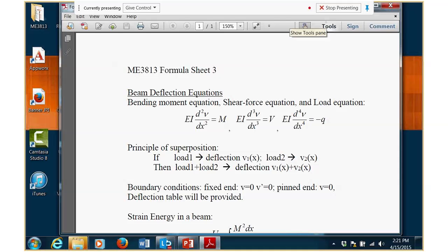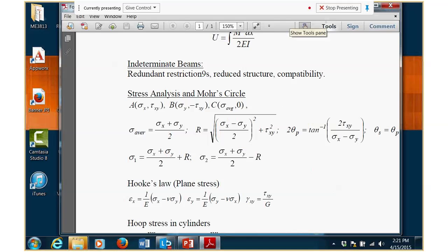And then you can solve that problem as a determinate problem, because that's what we call the reduced structure. And you need to know what a reduced structure is. For an indeterminate structure, you select the redundant load, change it to a force, then this structure becomes determinate. Okay. So that determinate structure, you can solve either with the equation method, the 3 equations we just did, or with superposition. Now again, whenever possible, use superposition. It's much easier. It'll save you lots of time.